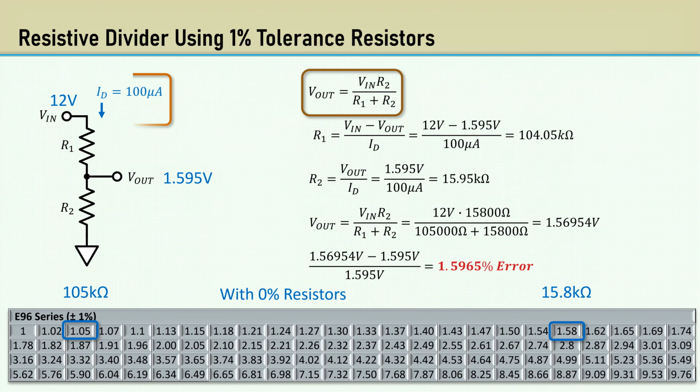The selection for the divider current is usually quite arbitrary. In most cases, the total resistance of the divider can be selected over a wide range of values. We can write software to find which two values in the E96 set are most accurate for the specific division ratio desired, and let the current in the divider be what it may, within reason, of course.